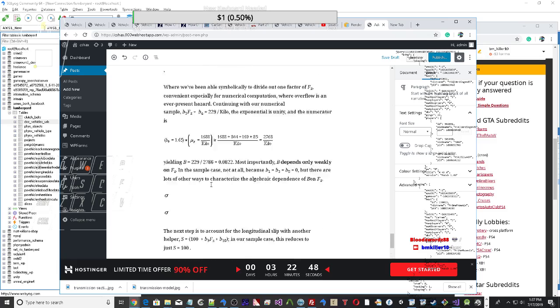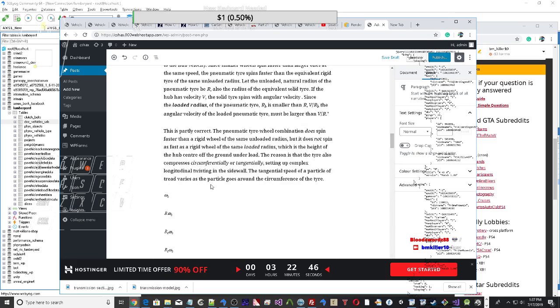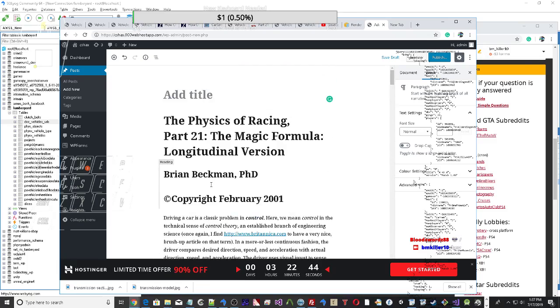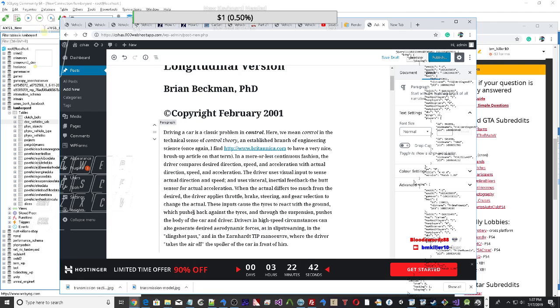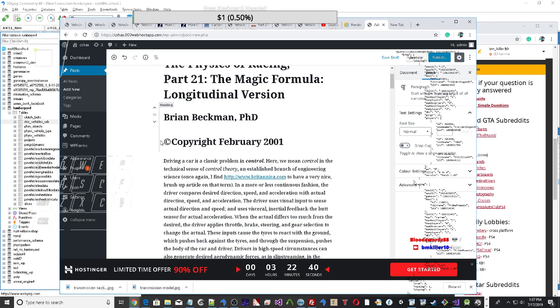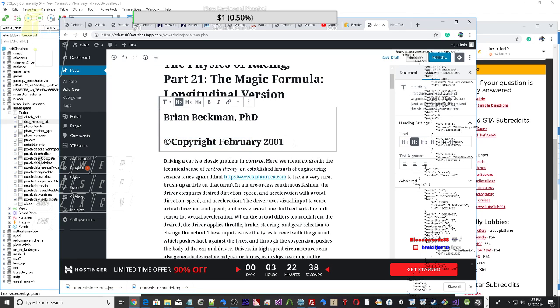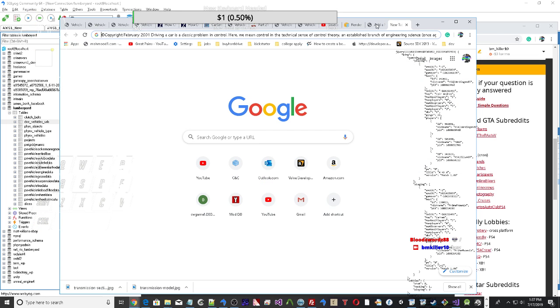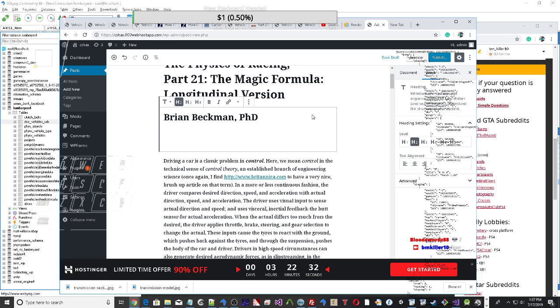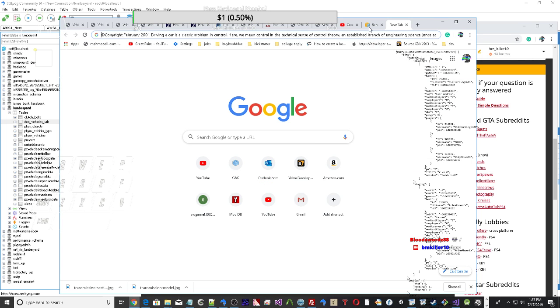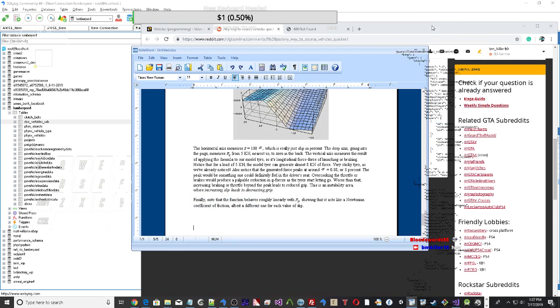Suspension force application point 0.3 meters below rigid body center of mass. suspForceAppCMOffsets[i] = PxVec3(wheelCentreCMOffsets[i].x, -0.3f, wheelCentreCMOffsets[i].z).